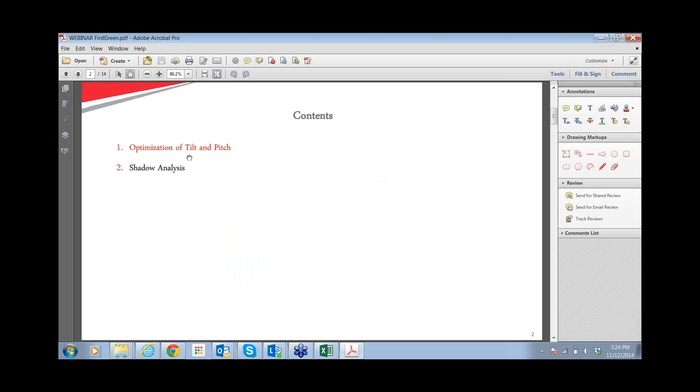Before starting my presentation, I would like to talk about something where Sanjay has left off, like true north. It is quite important to check true north before starting the array layout, and in practice in MAPC also, we do this meticulously, because there is always a difference between true north and magnetic north.